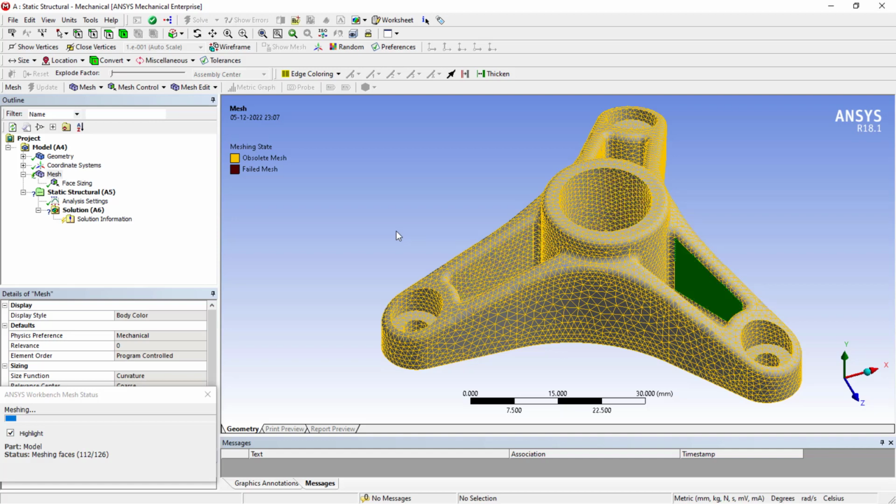So depending upon the mesh refinement, as the mesh gets finer, the time taken to create the particular mesh will also increase. Remember that. And if you want to solve this particular model with the refined mesh, it will also take more time. So if it is required, go ahead with the finer mesh, or else depending upon the convergence, you try to refine the mesh.